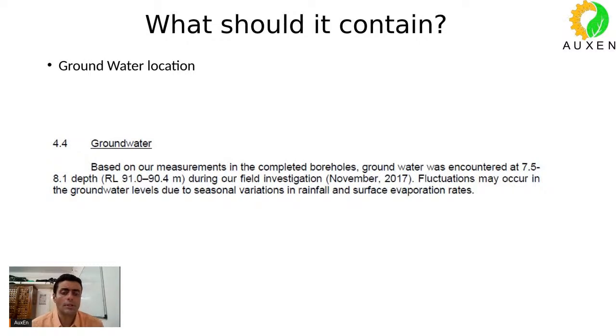If you are doing it in the monsoon months or just after the monsoon, your results may vary. And let's say if you are doing it in the winters, again your results will vary. So you may draw incorrect conclusions if you are testing the groundwater in, let's say, summer months. If you are testing in summer months, the groundwater table is anyway very low. So you may draw incorrect conclusions. So the season and the month in which the testing has been carried out is extremely critical.